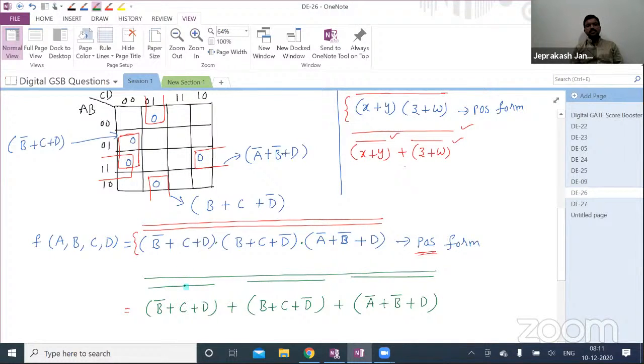Okay. Just one second. I will represent here once again whatever I have written earlier. Now in the question, what he has mentioned, you are allowed to use only 2 input NOR gates. In the choices, if you observe, in one of the choices, you have 2 input NOR gates. So whenever you are allowed to use only 2 input NOR gates, you can give only 2 inputs at the same time, right?